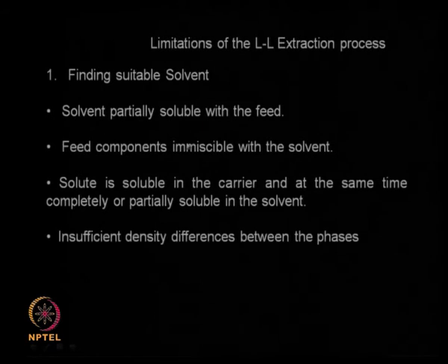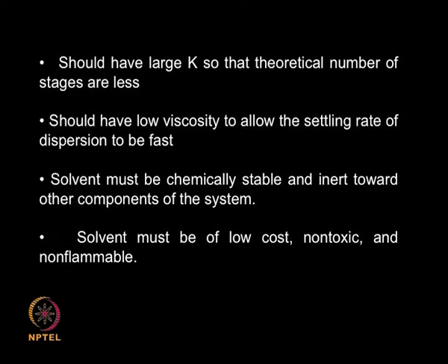If the feed components are not miscible with the solvent, you are not going to get a good mass transfer and movement of the feed components into the solvent. Okay. So, if the solute is more soluble in the carrier than in the solvent, the solute partition is also going to be a big problem. So, these are limitations with respect to the solvent.